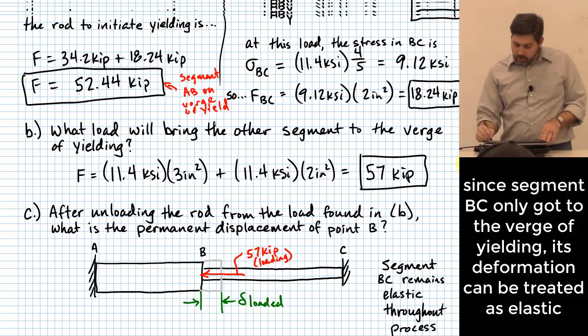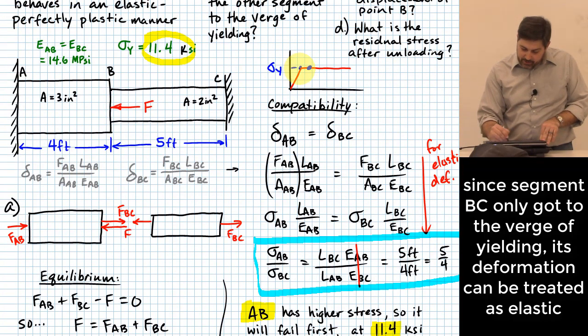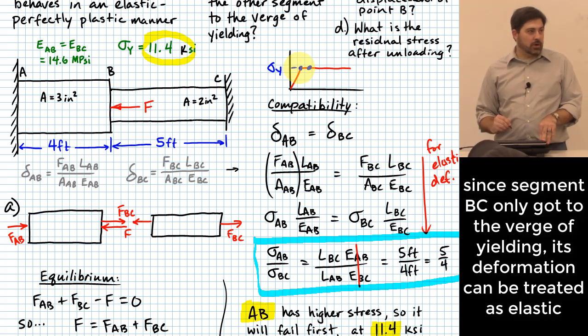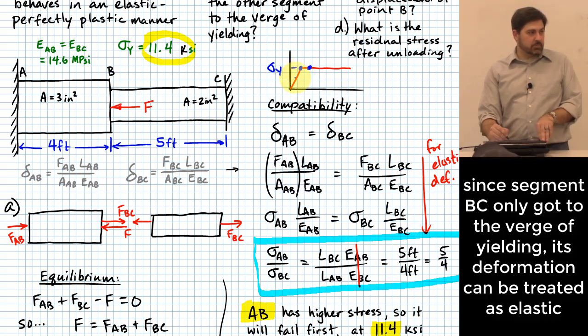That means for part BC on this curve that I was talking about right here, BC is literally sitting right on that little corner. That means that corner is actually part of both the slopey line to the left and the flat line to the right. That's a powerful point right there, okay? The reason why is that if you're on that point, you're still obeying the elastic formulas that we know for this rod, okay?